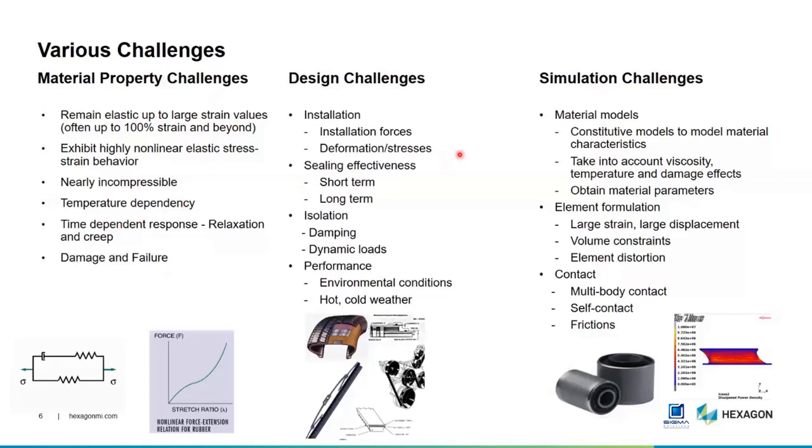Not only that, the design challenges would be, if you want to install the rubber seal, what are my installation forces? When you're installing rubber products, you want to make sure that the force the component sees is minimal. Also for rubber seals, the sealing effectiveness is important. You want to make sure that there is no leakage, so the sealing is effective in the short term as well as the long term.